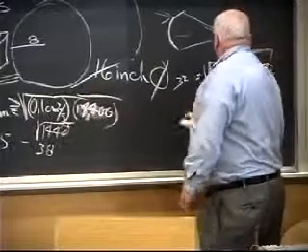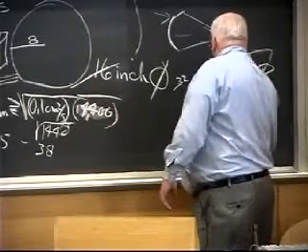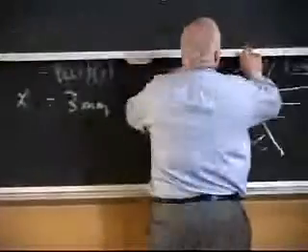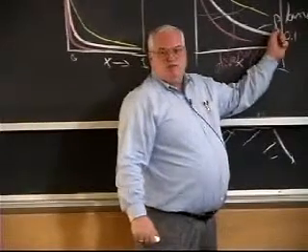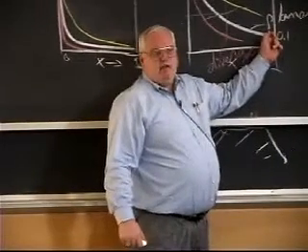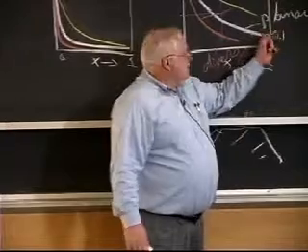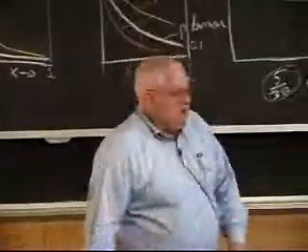So that's 32 over 38. Well, that's not all that far from 1, which means the very center is barely getting to 10% of the temperature that I want. I want 1600 degrees Fahrenheit. That means the center is getting to maybe 200 degrees Fahrenheit during this heat treatment.